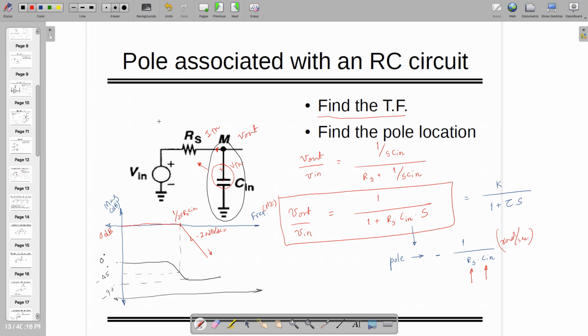While doing this, we are going to make all the voltage sources 0 and current sources open circuit, as we know. So apply that and then you can see that the effective Thevenin impedance is actually Rs. So that is going to be kept here, and in shunt in multiply with the capacitor which we were trying to formulate. Note that when we are doing this, and if you have more number of capacitors, do not consider other capacitors at that time, right?